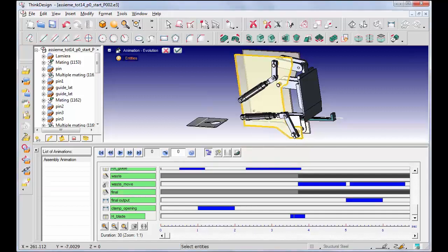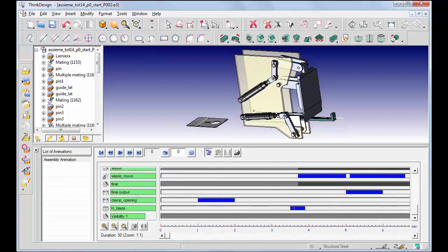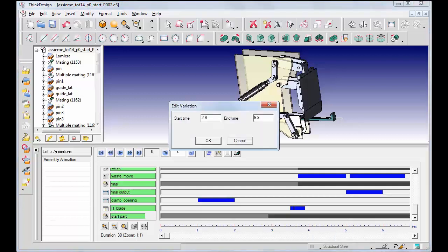We have to select the involved entities. The entity involved in the evolution in our case is the last used component. Let us then select it, after renaming the new evolution and setting the new variation, remembering that this evolution indicates in which time range the entity will be visible by setting the start time to 204 and the end one to 362.